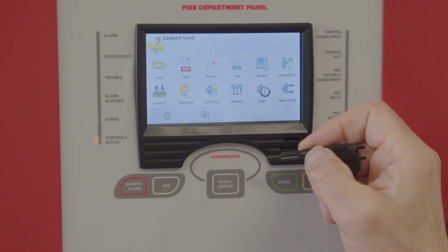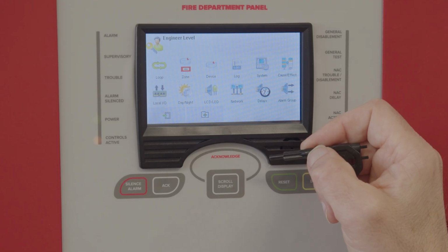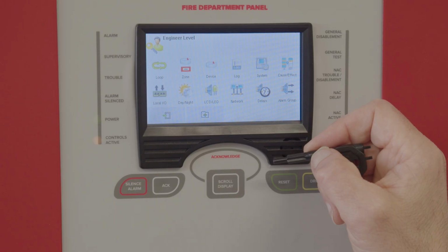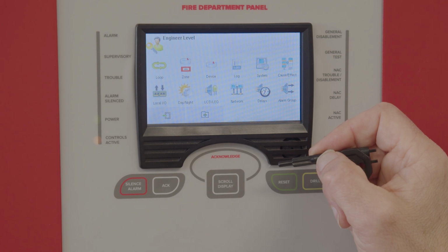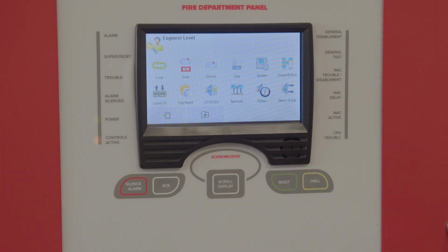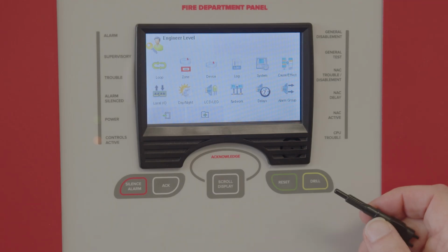When all devices in the list are as anticipated, press the door symbol to exit and ensure you select the tick when prompted to confirm changes. The auto search procedure is completed. Once the database in the panel has been updated, the devices can then be edited for configuration either on the panel screen or using the PC configuration tool after uploading the panel data.